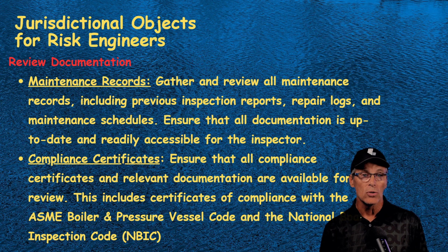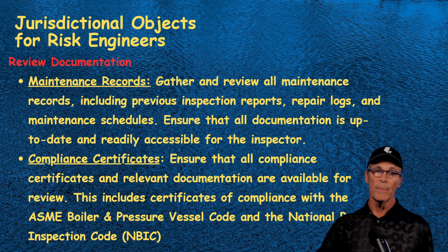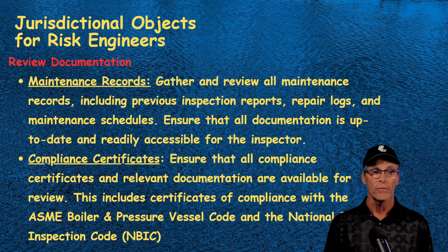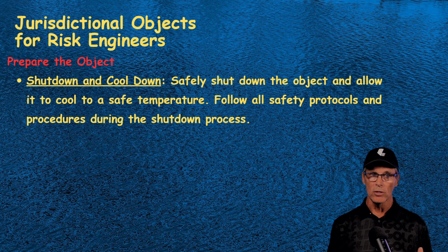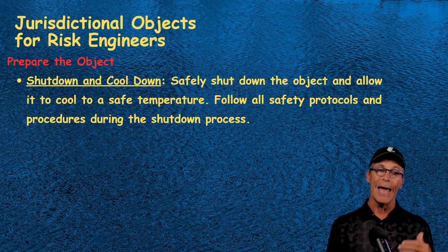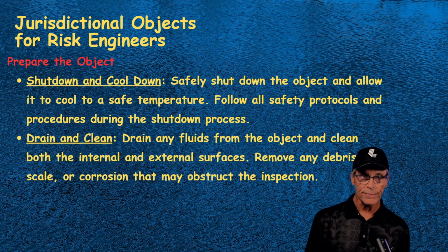Compliance certificates. Make sure that you've got them all. When I go into facilities, I typically see them put on a bulletin board near the control room, where all the licenses for the operators might be too. It depends on the state. All right, prepare the object. Again, you have to shut it down, cool it down, clean it up, and make sure that when they go to look at it, they can access it, and that if scaffolding needs to be built, they've got scaffolding.